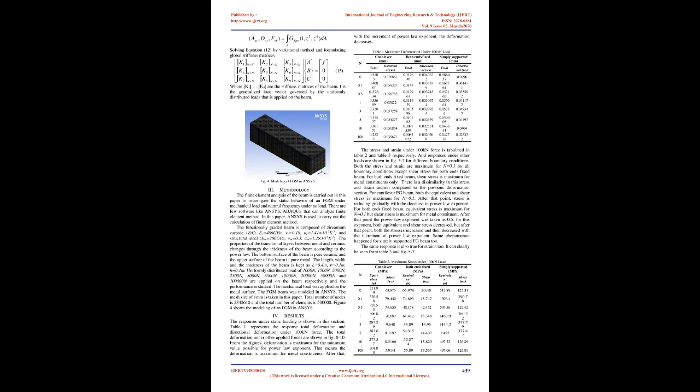In the FGM, the effective properties like Young's modulus E, Poisson's ratio V, coefficient of thermal expansion A and modulus of rigidity G vary continuously through the thickness direction according to the power law, equation 1. Here, n is a non-negative variable parameter which describes the material property variation through the thickness direction. Constituents C and M stand for ceramic and metal respectively. It is clear from equations 1 to 3 that the variation of Young's modulus along the thickness direction of an FGM is shown in figure 3.